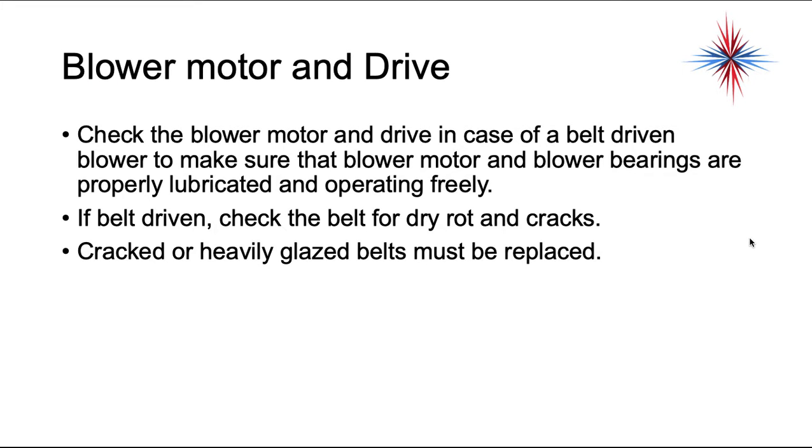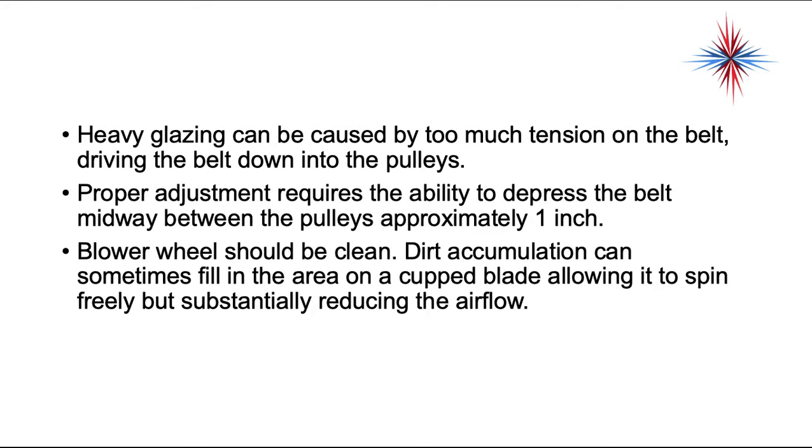The next thing you want to look at is the blower motor and drive. Check the blower motor and drive. In the case of a belt-driven motor, you want to make sure that the bearings are properly lubricated and operating freely. If belt-driven, check the belt for dry rot and cracks. Cracked or heavily glazed belts must be replaced.